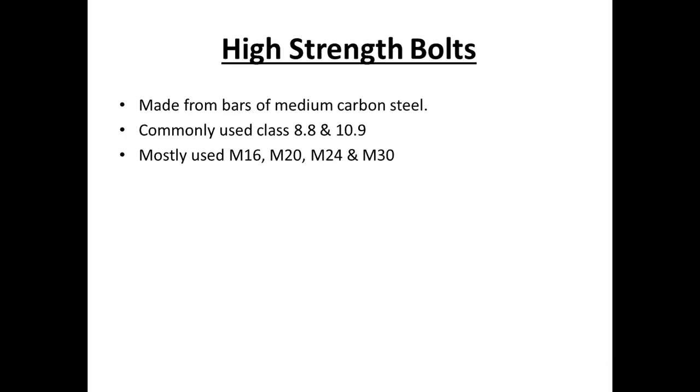You read that the grade is 8.8S, 10.9S. The suffix S denotes high strength structural bolts, right? So in 10S, the 10 is the grade, and S denotes high strength structural bolts.